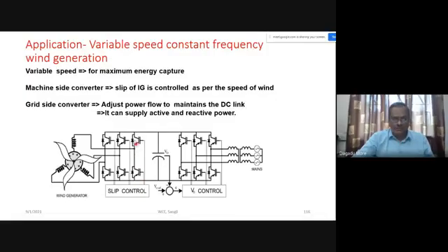Here we are using a PWM technique, and with it we can decide the frequency of the voltages at ABC. We can find out the frequency, and it is possible with the PWM technique to adjust the frequency of this PWM rectifier. It is a rectifier, but we can have AC here. The voltage appearing here will be AC, and its frequency can be adjusted.